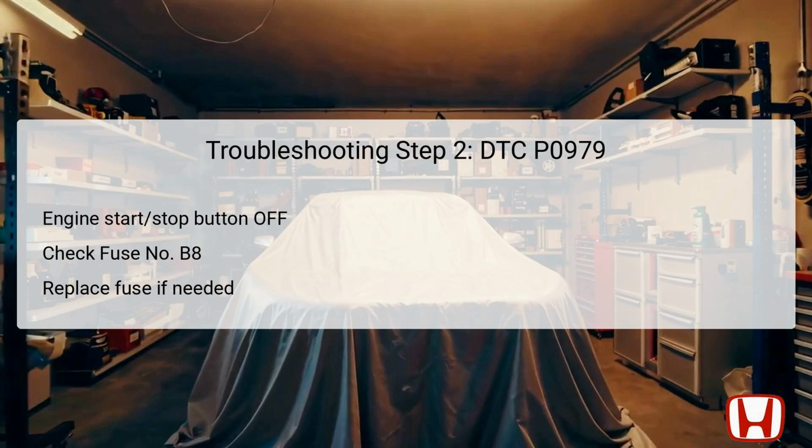However, if the fuse shows signs of damage or is blown, it will need to be replaced with a new 10-amp fuse. Upon replacement, it's crucial to recheck the system for further issues. If the new fuse blows again, it indicates a short to body ground in the circuit that would require further investigation to locate and repair.